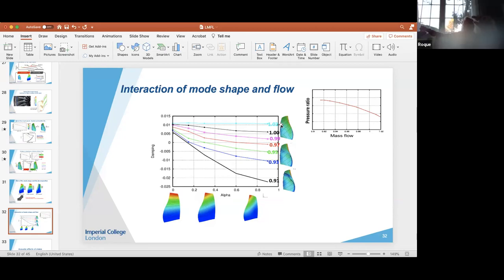Yes, because you have migration. Because you have a mild separation, and because of the centrifugal forces, you get some migration inside the boundary layer, because you are looking at what is happening very near the wall. That probably changes the pressure distribution as well, but your separation is really very small.